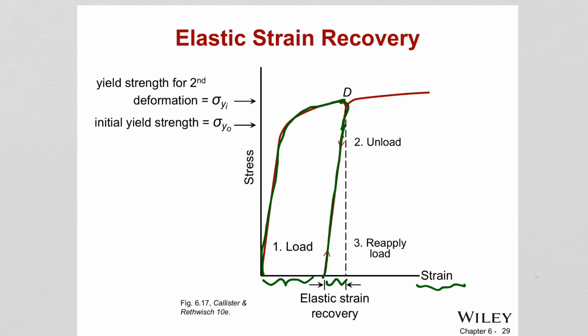if you actually repeat the same experiment on the same material, you apply again, let's choose a color here, another stress, again elastic deformation, this time the yield strength will be higher and it keeps deforming plastically. The reason is, once you deform the material right there plastically, the strength of the material increases. That's why deforming materials actually increases their strength. They call this cold working.